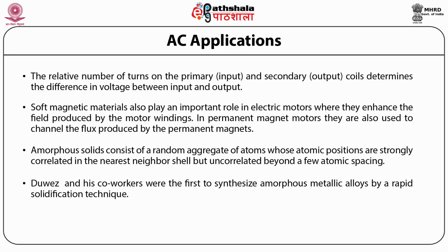Duwez and his co-workers were the first to synthesize amorphous metallic alloys by a rapid solidification technique. This pioneering work initiated a spurt of research activity on synthesizing and exploring the exciting new phenomena exhibited by various amorphous metallic alloys. Amorphous alloys can be obtained through two diverse routes. One is rapid solidification, for example melt spinning, and the other is mechanical alloying.